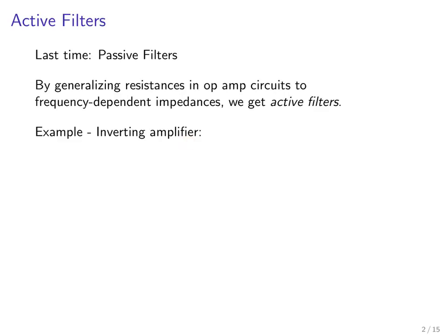The simplest example of this is an inverting amplifier. Whereas we would typically have an input resistance and a feedback resistance in an inverting amplifier, now we can generalize this concept so that we have input and feedback impedances. So this will be Z sub I, the input impedance, and a feedback impedance, Z sub F. Here's our op-amp, to V out.